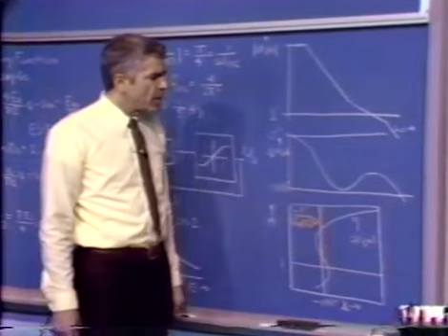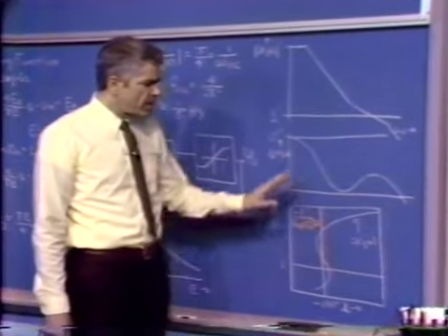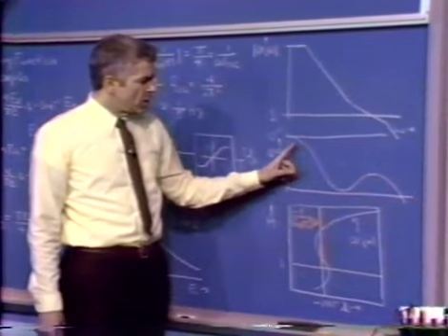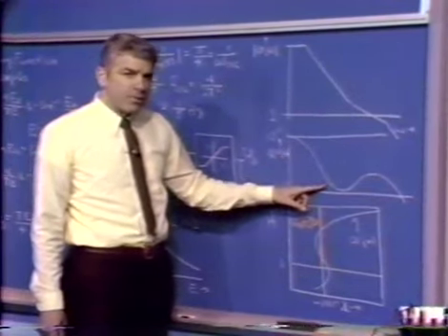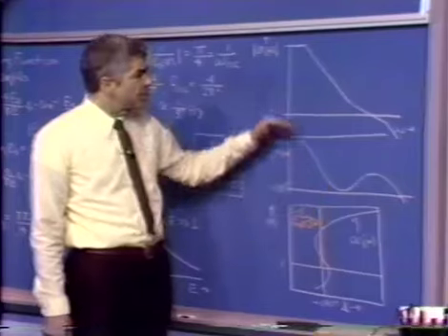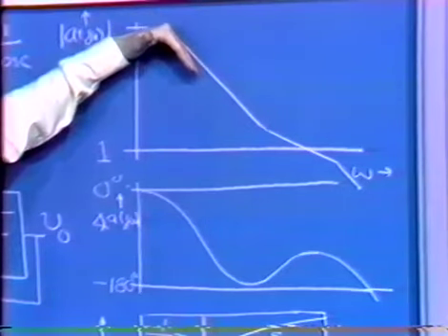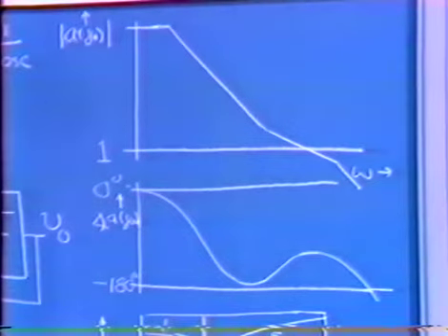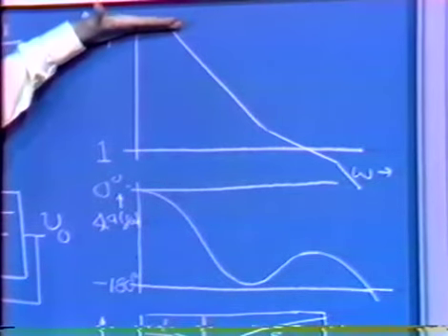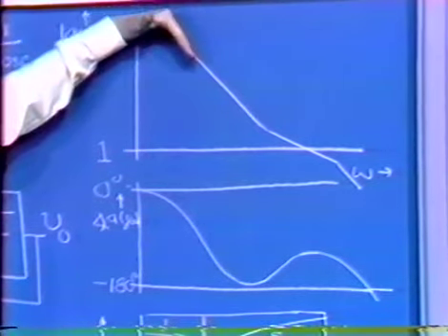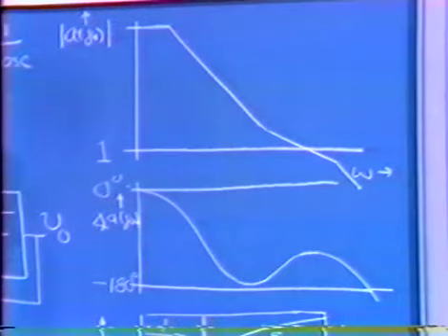Another case where we didn't actually draw the Bode plot in great detail, but we spoke about it, was our operational amplifier example when we used two-pole compensation. Again, we get a curve for the open loop gain of the operational amplifier that's very much like this when we use two-pole compensation. We have the DC gain of the amplifier. We then get into a long 1 over s squared region.